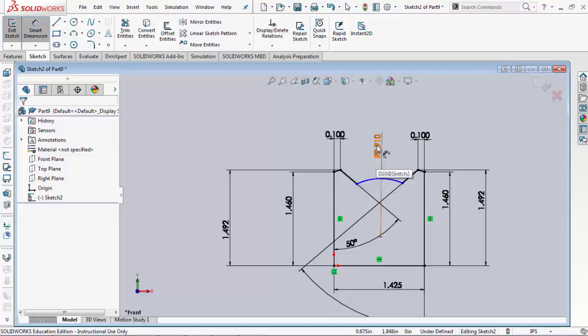It really is not important where I place these dimensions, as long as the dimensions are there to fully define this object. As you can see, the arc is the only line that is not fully defined. And so I already have the size of the arc, but I don't have the position for the arc. And typically the position has to be placed according to the center point or some other dimension. So there's 2 dimensions that are missing.